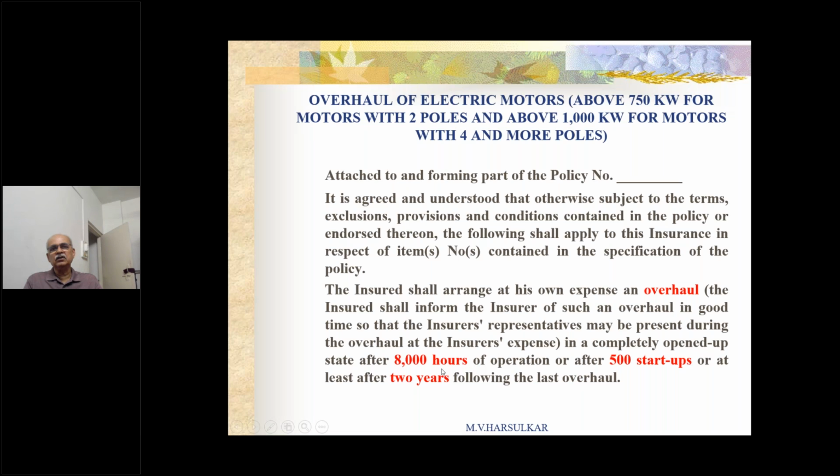This is the first condition, 8,000 hours or 500 startups, or at least after 2 years following the last overhaul. So these three conditions are there. If you say this 8,000 hours, it comes to about 2 shifts per day, or 2 years. If it is working three shifts, in that industry, maybe it will be less than 2 years. And 500 startups depends on how frequently you are stopping that machine and starting it. So whichever is earlier, the insurance company will say that you should have done the overhaul by then.